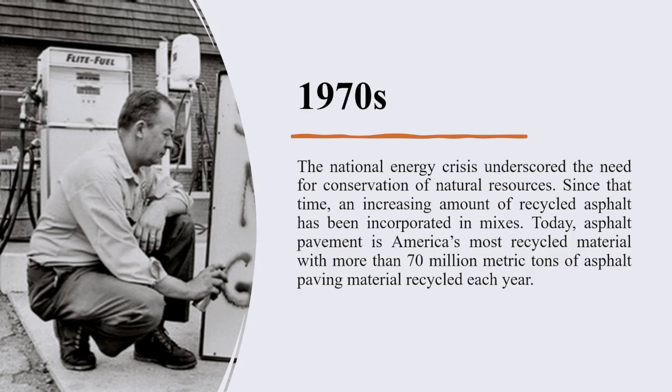And that's where most of the standards were developed in the United States, including even the geometrical standards, like the width of the lane. It is 12 feet in interstates. It can be dropped to 11 feet in arterials. It can be 10 in collectors. And some people are calling even for 9 feet in the local, residential areas. There are locals, collectors, arterials, and freeways. So freeways, 12 feet, that is based on the Highway Act.